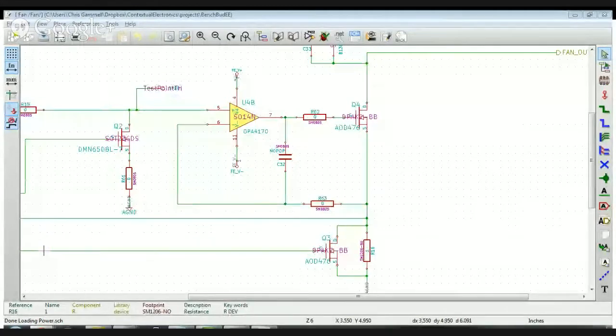James also wrote in the Q&A section you'd like 250 microamps of current control for semiconductor testing, for generating VI curves, which is actually what we talked about. We talked about doing this with finer control for testing out the opto, so actually testing the LED characteristics on the primary side of the opto. So that is another interesting use case. That would definitely be finer control.